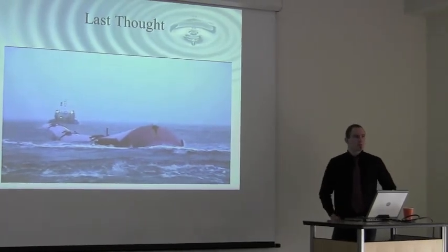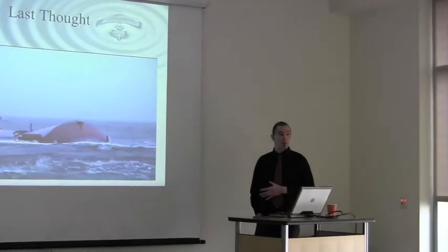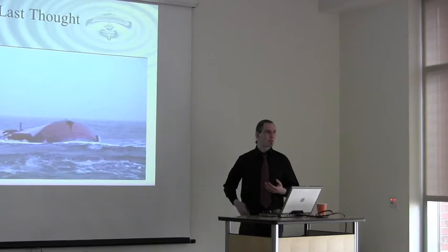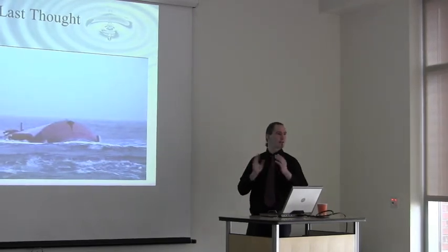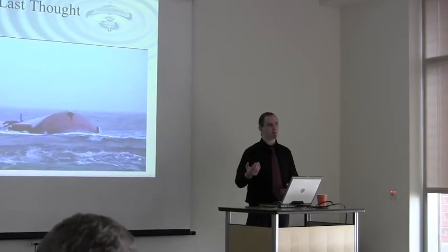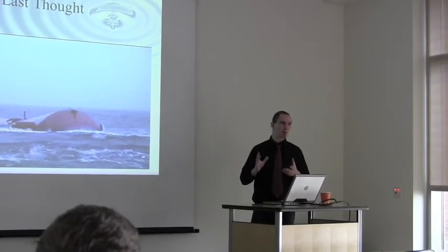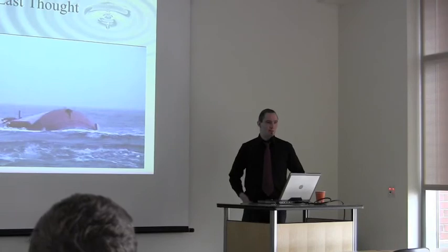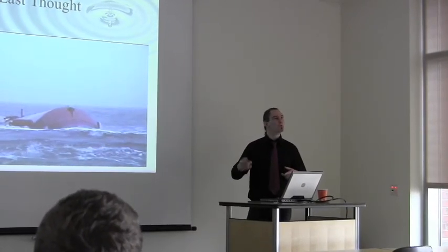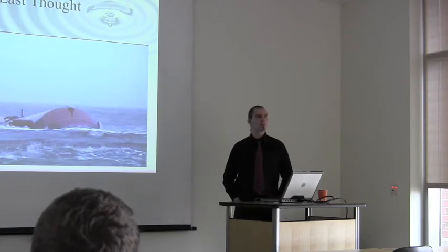So, yes and no. I really wouldn't recommend a tall, slender cylinder because even as a surging device, you get too much self-circulation. There's no build-up on the front face as you're surging backwards and forwards. So I would be looking more at changing the cylinder in some way so that it interacts with the particle flow rather than trying to make it a conservative device.